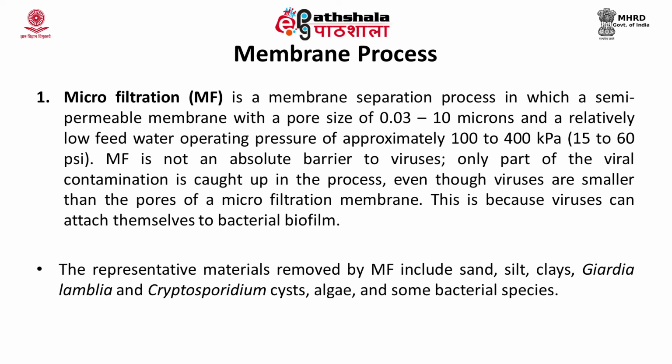As microfiltration is not an absolute barrier to viruses, only part of the viral contamination is caught in the process. The primary impetus for the use of the microfiltration process has been the increasingly stringent requirements for removing particles and microorganisms from the drinking water supply. Additionally, there is an emphasis on limiting the concentration and number of chemicals that are applied to the drinking water in the treatment process. So, these membrane filtration processes are safe to use.